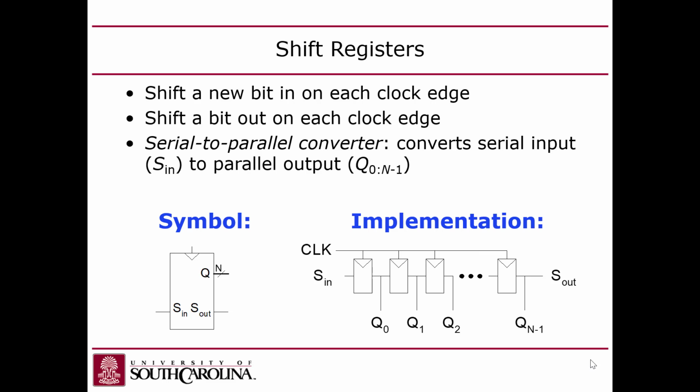So when you configure the FPGA, I don't know if you guys noticed this or were annoyed by this, but it takes like 20 to 30 seconds. And you're like, the configuration file isn't really all that huge, it shouldn't take that long. But yeah, you're shifting in. JTAG makes a big shift register. In the case of an FPGA, you have to shift in a lot of bits. You have to fill up every LUT and every switch and all the muxes that are inside the LEs, the logic elements. So there's a lot of bits to shift in.